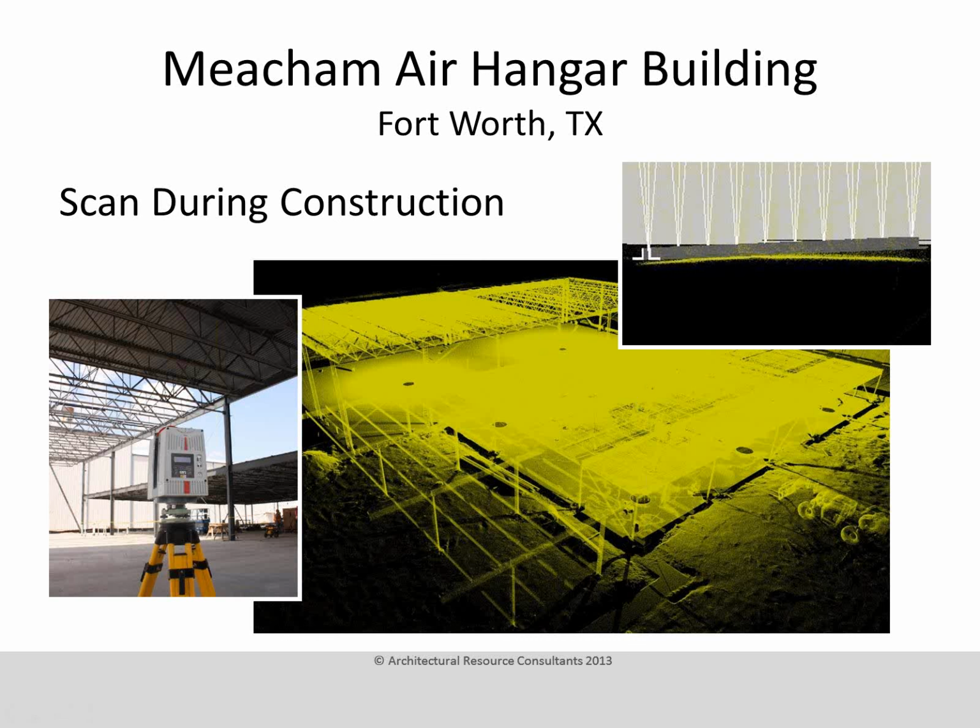Again, you can compare the model with the scan data using a product like Navisworks. Scanning's great for modeling rocks. I don't know how you would model a rock without a scan. But it's very good at capturing even the most organic shapes and creating a model from it. Products like Geomagic or Polyworks or 3D Reshaper can be used to model elements such as this.